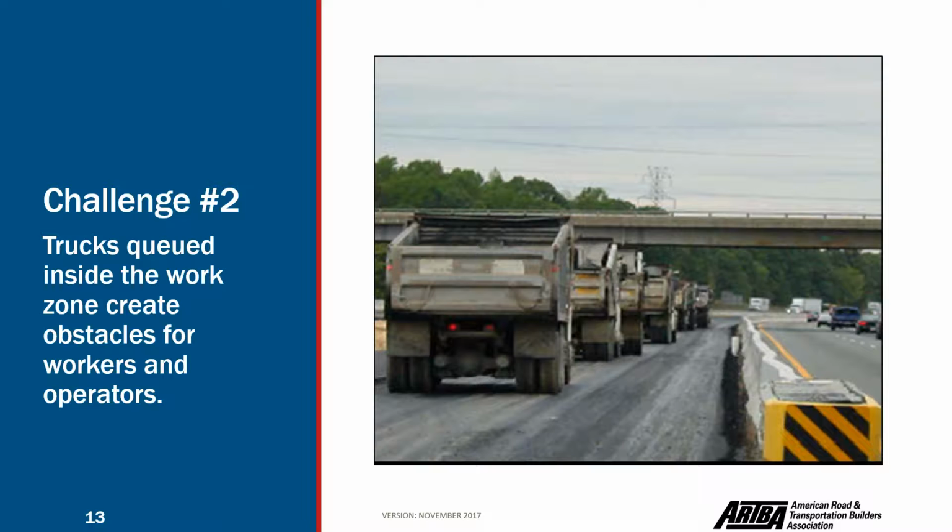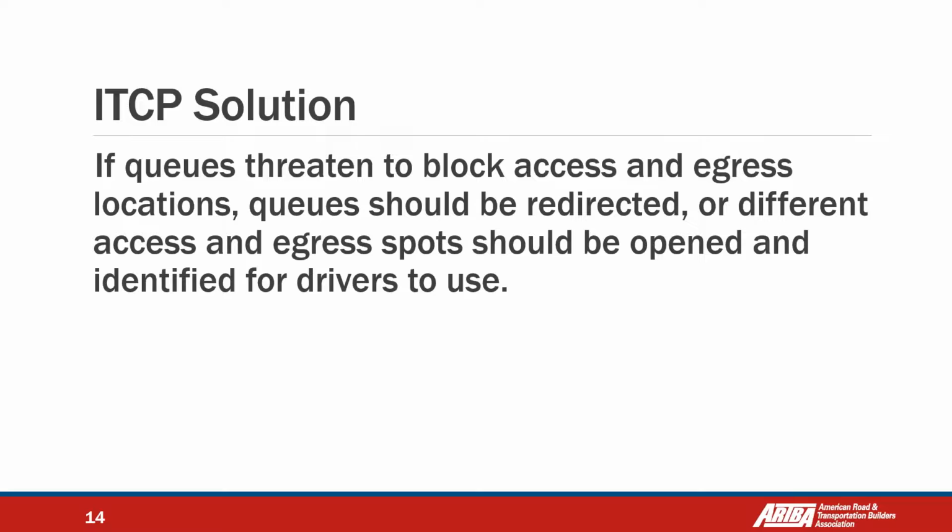But if suddenly we are asking dump trucks to arrive and use the brakes and prevent an accident, if this is the access zone, we are going to create a problem. So the idea is to provide enough space for deceleration when they arrive to the work zone, and do it safely. Okay, and of course talk with them about blind spots, especially because workers on foot could just walk on the area, and also talk with the workers about blind spots.